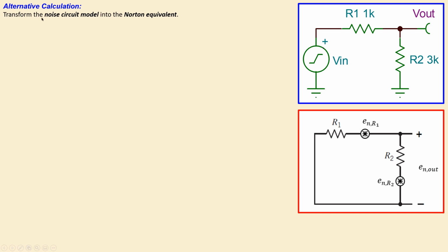So I can say transform your circuit in a noise model where you don't use a Thevenin, actually series combination of the resistor and the noise voltage source spectral density, but use a Norton equivalent, which is then the R1 as a resistor in parallel with the current noise spectral density. So then the required parameter for that one is the equivalent resistance seen at these nodes.